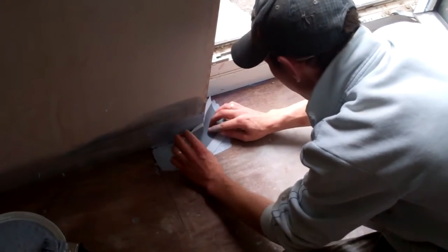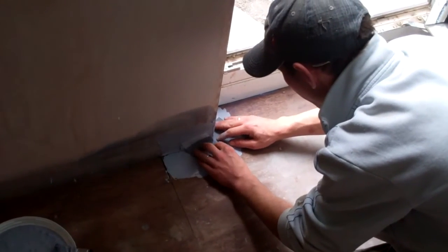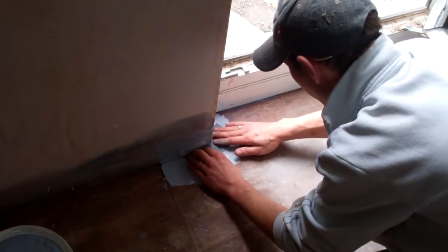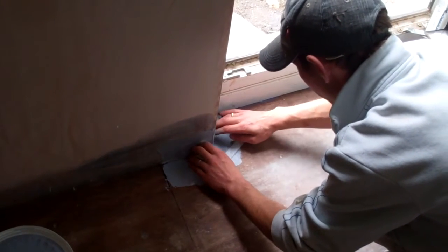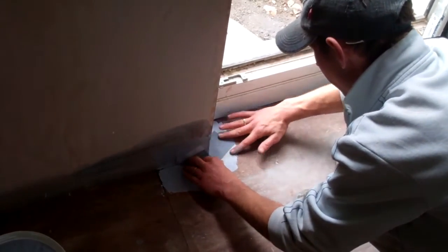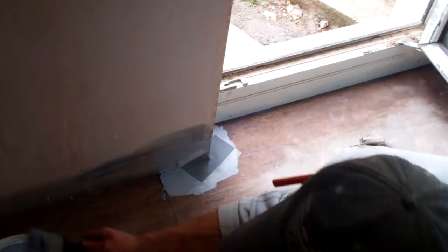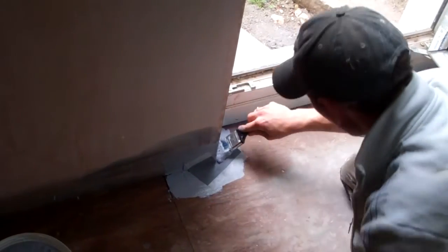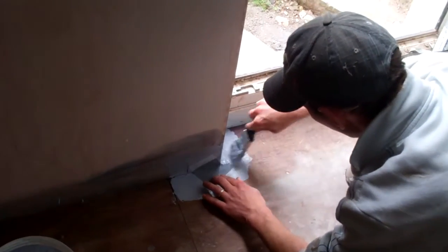A second piece of tape is cut exactly the same as the first piece, but this time it is applied diagonally across the corner with the cut facing upwards. The corner is then overpainted with Aquaproof compound, making sure all tape edges are well bedded in and laying flat.